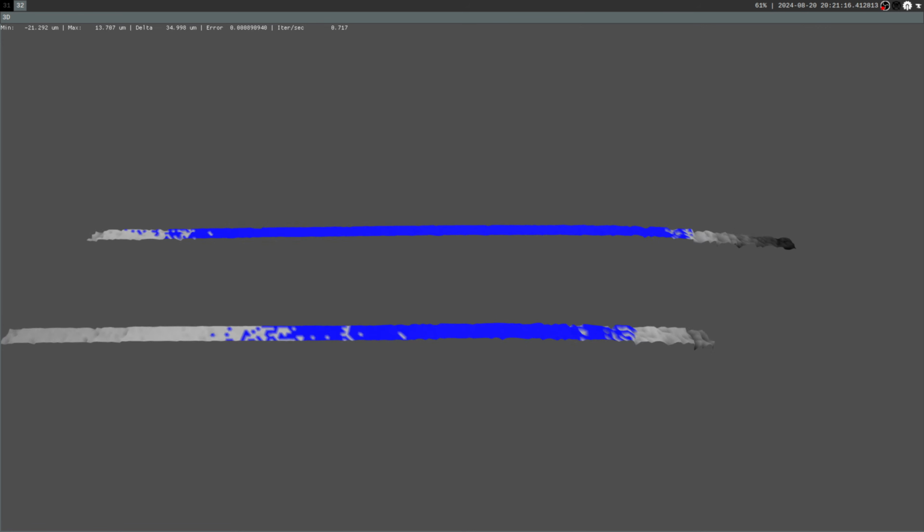Unfortunately, that's really hard and very subjective. It's kind of like feeling out where sticky spots are. And it's really hard to feel that out because there might be a spot of oil on there. There might be some grease on there, some debris, some leftover chips, a raised bump from a scratch. And obviously you try and clean it, you try and wipe all that down, but inevitably that is part of your measurements, and it's going to lead to you making some mistakes.